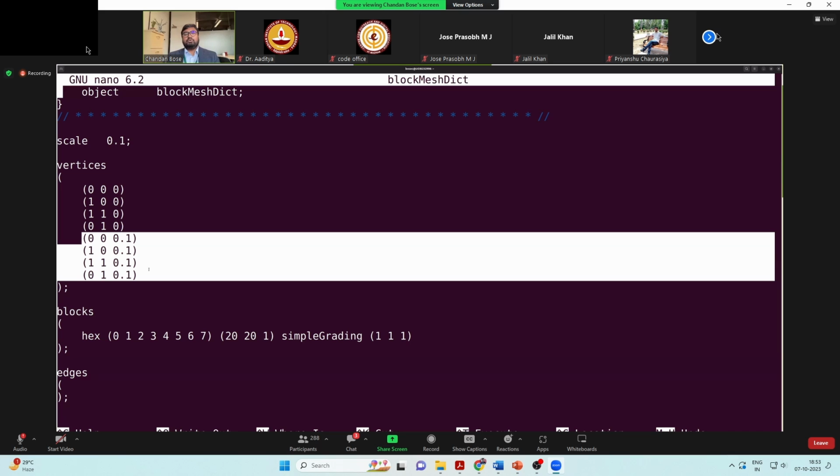To define blocks, because its name is blockMesh itself, that means we first create blocks with the vertices, then mesh each of those blocks. All right. And if needed, we define edges, such as if we have an arc in our mesh, we have to define the arc separately, and so on and so forth.